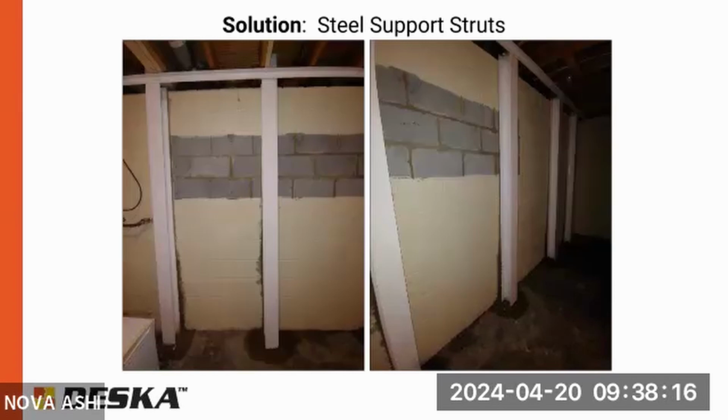You could have what's called a monolithic footing, which is where the slab is built down around the perimeter of the foundation and is actually structural. But if you're seeing large cracks in the slab and the slab is structural, you're probably going to see other warning signs as well. So if you only see cracks in a slab and you can see, say half a block, not a full block at the wall, then more than likely it's not structural if you don't have any symptoms. But if you can see the full block or you can't see it at all, but there's a lot of cracks in the slab and you have cracking in the walls or areas above, then I would treat it a little bit more seriously.